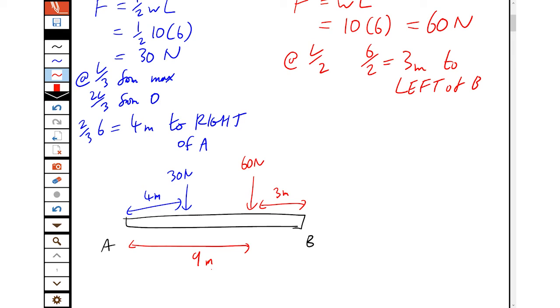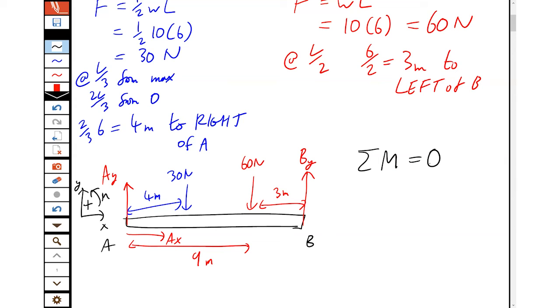And then we have the support reactions. A is a pin, so it has a vertical and horizontal unknown component. B is just a roller, so it has our friend the vertical unknown. And then we're on to our standard procedure. Plug in our axes. We don't want to make a mistake with directions, so we always remind ourselves which way is plus. Always start with the moments. The sum of all the moments around some pivot is 0. We choose the pivot point with the most unknowns, which is A. B would actually work in this case, but we always practice our rules.